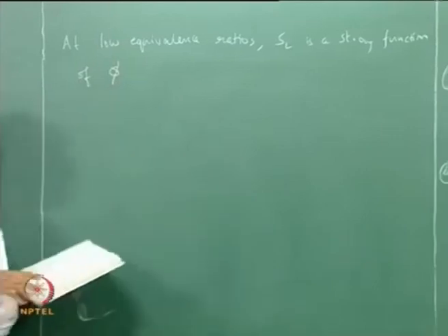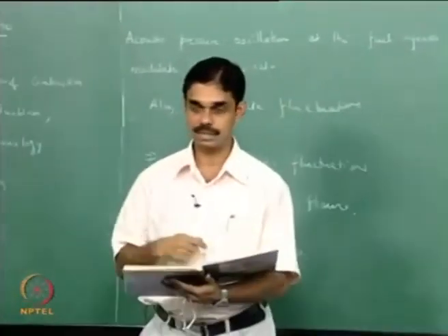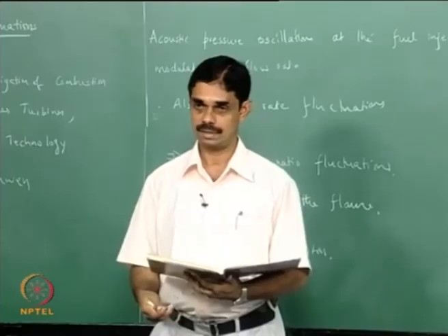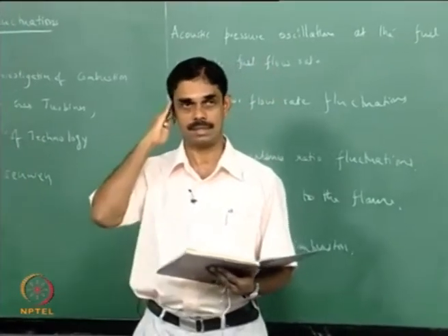So a small disturbance in phi can make actually a large disturbance in SL, which will lead to a large disturbance in heat release.